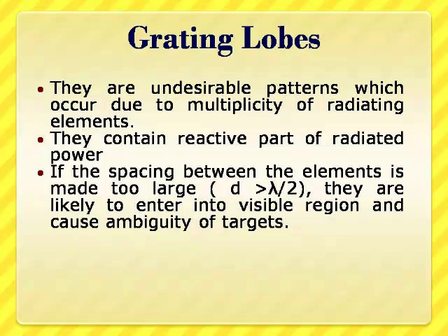And this is the disadvantage which we have to accept if we go for a spacing of 0.5 lambda between the elements or more. If we don't practice this 0.5 lambda spacing and go for higher spacings in the design itself, then the grating lobes will be present even under non-scan condition and give rise to reactive impedance of the elements, which is more troublesome.